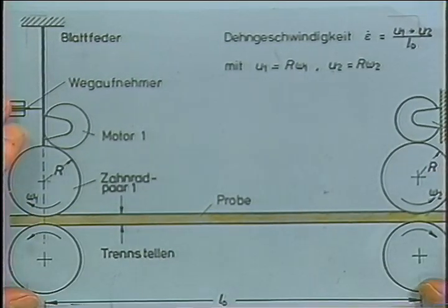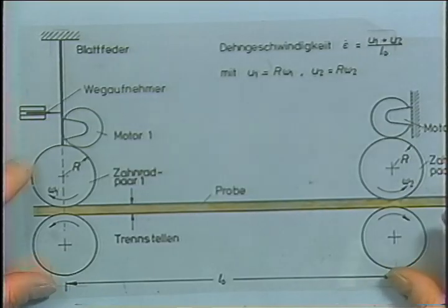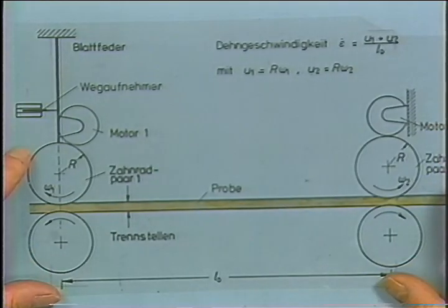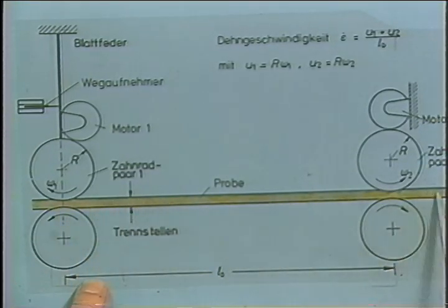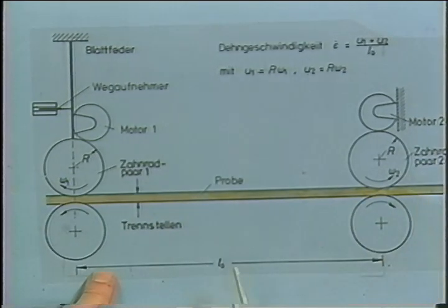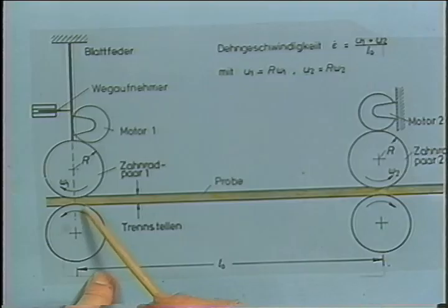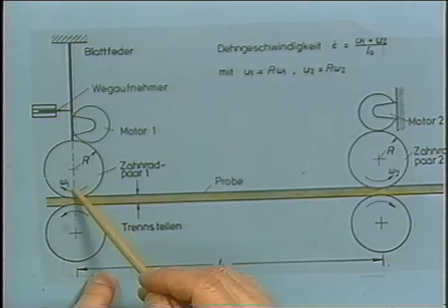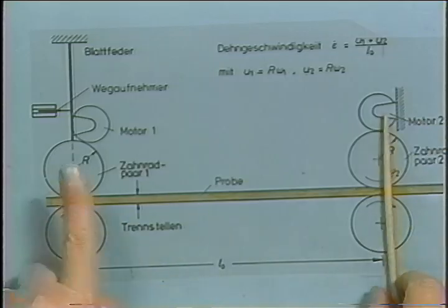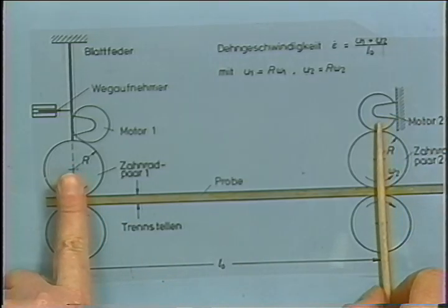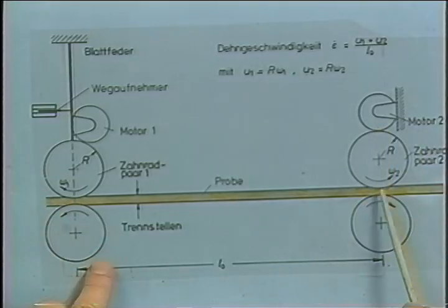A very nice experiment has been proposed by Meissner, and in '71 he had a famous publication on that. He simply took a long rod-type sample and floated it on top of an oil bath. So the heating comes from the oil bath itself, and he grabs the sample with pairs of rollers on this side and also on the other side, and those rollers move the sample always away out of your test section in both directions. You always have new positions of grabbing while this experiment is going on.